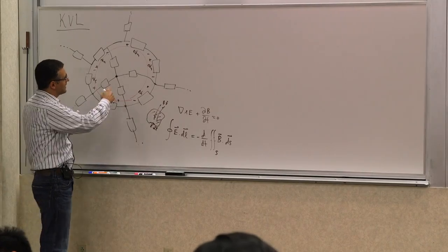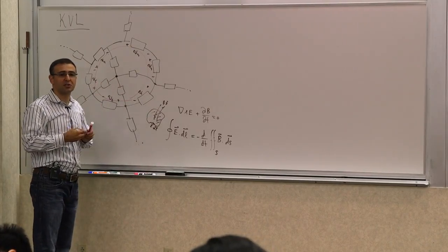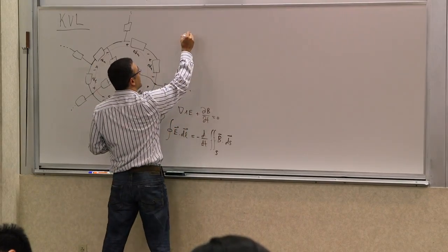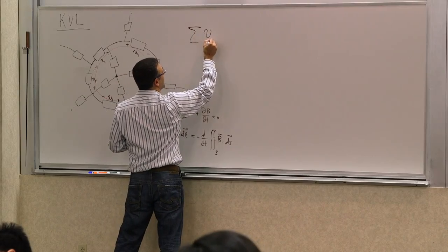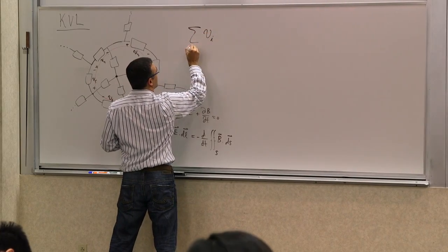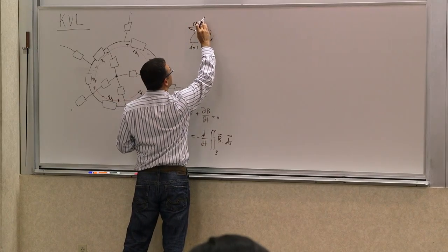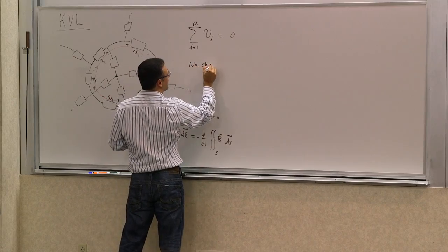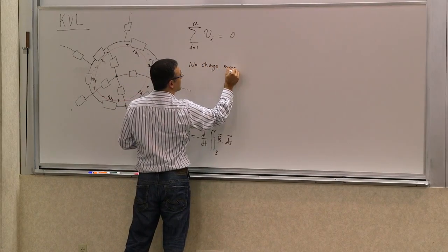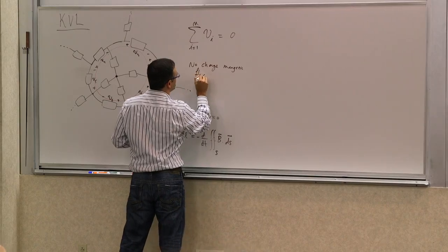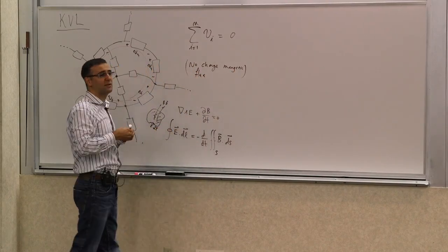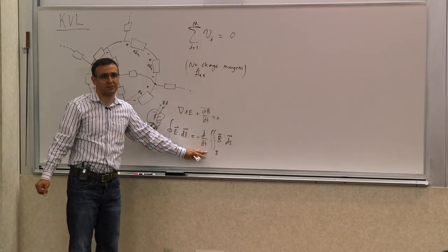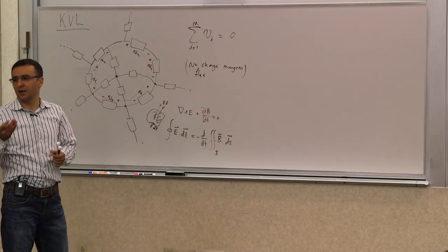So now it's basically the algebraic sum of all these voltages, if there is no magnetic flux, which is the assumption that you make here, that the sum of Vi for i equals 1 to m equals 0. No changing magnetic flux. So in other words, if you have a fixed constant magnetic field, it's not going to matter because of this derivative. If you have a small enough loop that doesn't pick up enough, it doesn't matter.